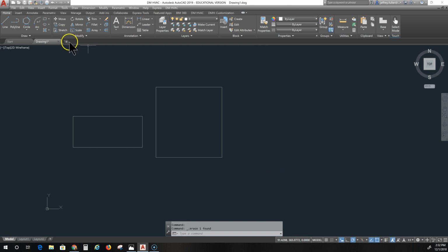Okay, let me do that over. I hit too many buttons. Okay, polyline, straight line. Now I'm going to type A and enter, and I can put an arc right here on the end. You can kind of see faintly where that arc is forming out to the right. And once I click, there's the arc. Go back to the line tool by typing L and enter, and I can pull that out and line it up. Okay, go back into A for arc, and there we go. And I think this will be a question on your test.